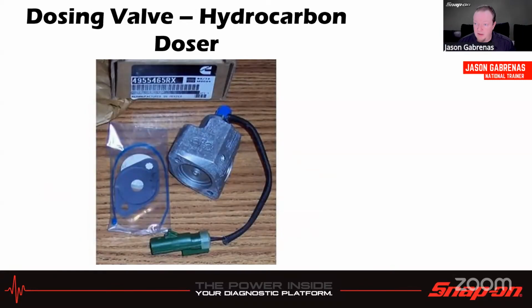The dosing valve is going to be used to add the extra fuel into the DPF in order to light it up and make it hotter. So that is just an example of one right there. It looks like it's from Cummins. So that's a hydrocarbon dosing valve. It's basically a fuel injector. Upstream from the cat, the fuel will light when it hits the cat and then warms the DPF enough to regen soot. It's plumbed to a diesel fuel line, adds fuel to the exhaust for active and parked regens. Some also have air plumbed in them to better atomize the fuel.